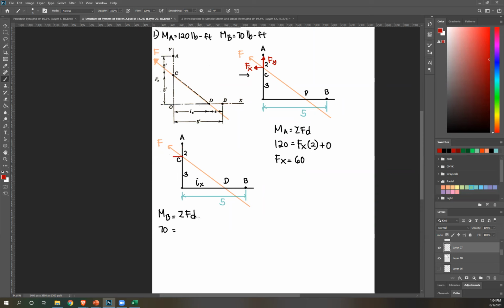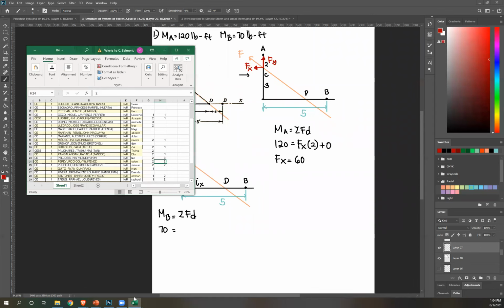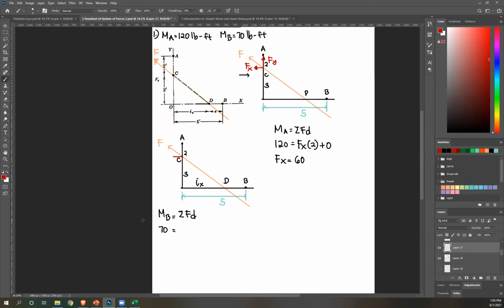So technically, you're both correct, Naomi and Mendoza. Once again, I can't choose D yet since I don't know this. So we're left with this option at C. So this is Fy, this is Fx. Let's create our equation. Let's start with Fx. Rotate Fx about B. So that's counterclockwise, right? So that's negative Fx.